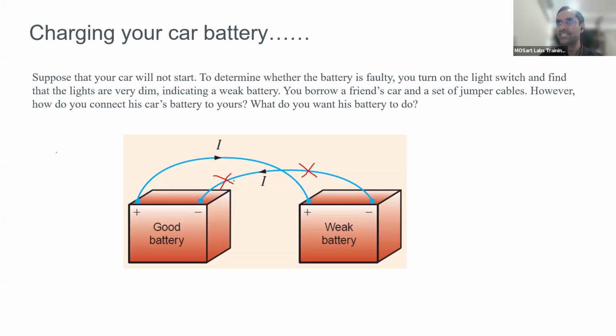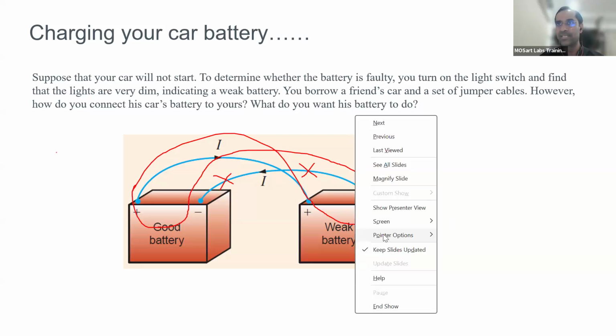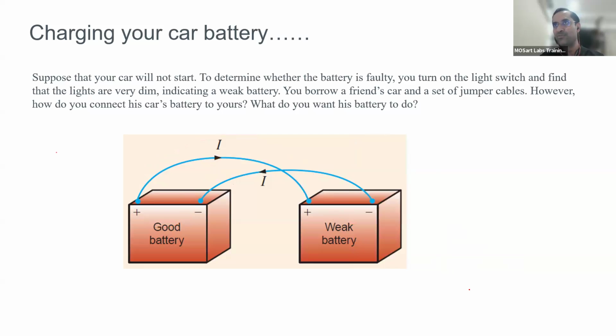So are you clear? The way to represent a circuit is not only showing the forward current path, but you should close the loop. So current goes from here, it charges your battery, there is an ionization that happens, then the current should flow back from your negative onto the positive side. So the loop is complete. Every circuit that you build and analyze, you have to close the current loop. Right? Fundamental principle of circuit analysis. If you don't close your current loop, you'll be violating basic principles.